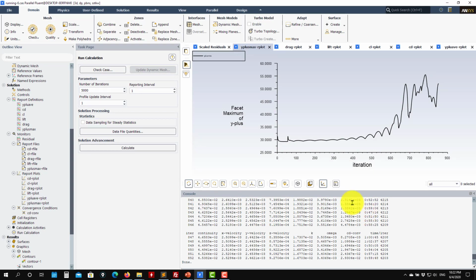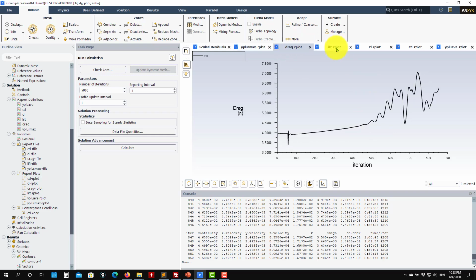Okay, so let me stop after 850 iterations, compared to the previous one that we had using the coupled solver. So just to show you, this behavior is clearly very different from what you see here, the one that was the coupled solver. Now the SIMPLE is capturing a different physics. So it's not wrong, it's just telling you that you have unsteady behavior, okay?